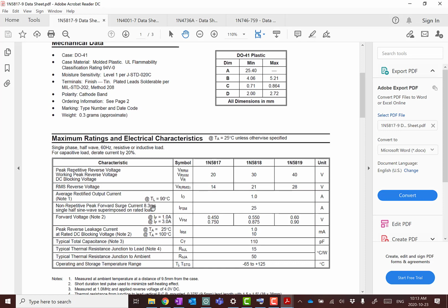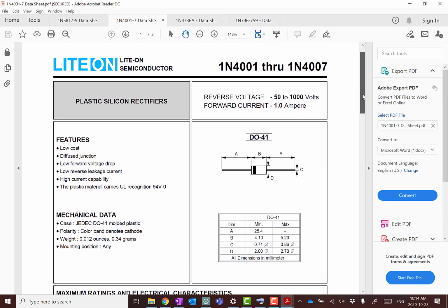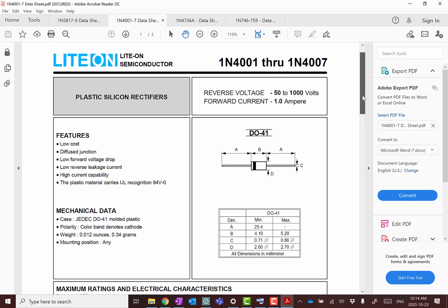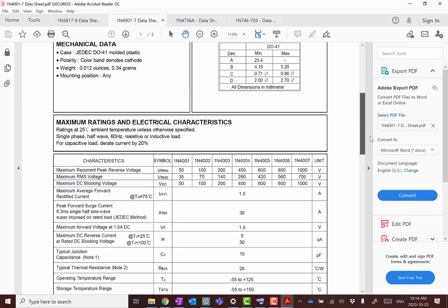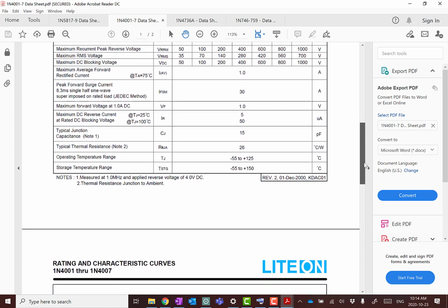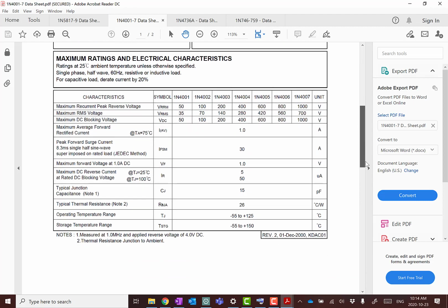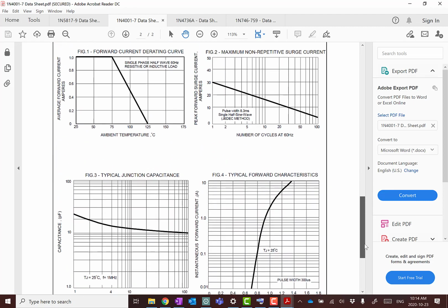Although this is silicon, it's manufactured to have a lower voltage drop, and we see that it's in general lower than a typical diode. Whereas this very characteristic silicon diode has a forward voltage drop that is more typical of what we expect. I guess this is showing a maximum forward voltage drop of 1 volt. That's for high levels of current.